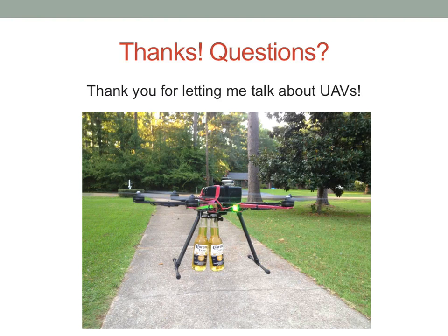So for terrain following, that sonic capability only has a certain amount of range. So you would want to use an active technology like a little LiDAR scanner to ping the ground and then get your range so it could adjust for that. But all those technologies are being developed and are on drones, but are being used for slightly different purposes. And so it's just a matter of time before someone says, let's turn it this way and use it for that purpose instead of something else.